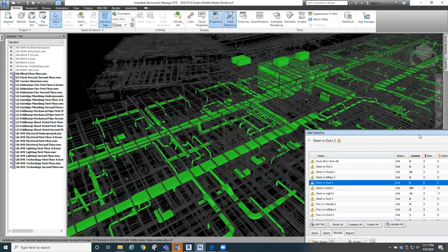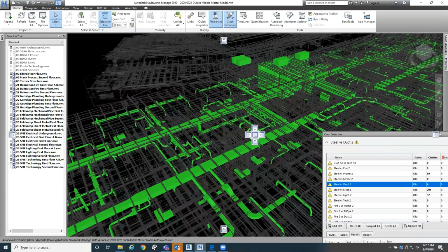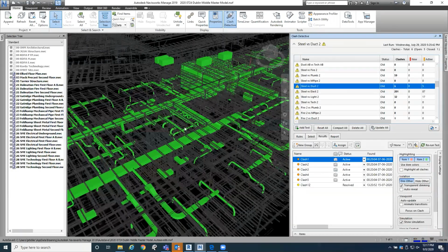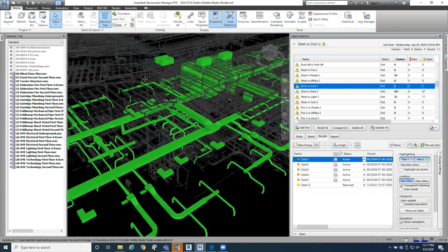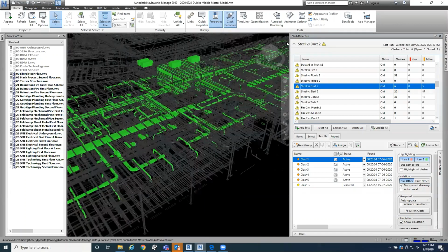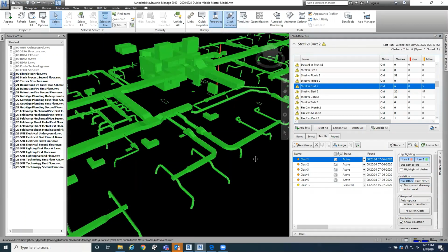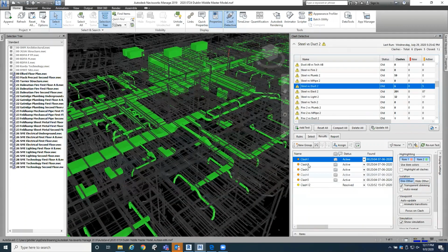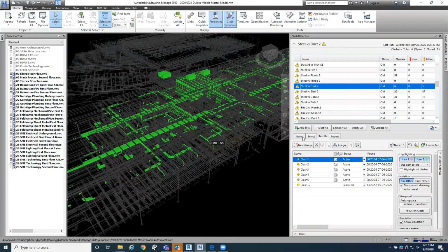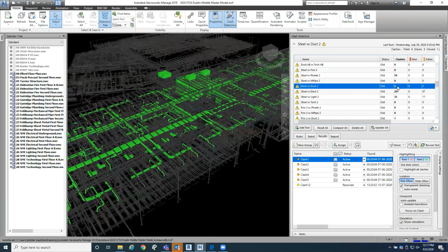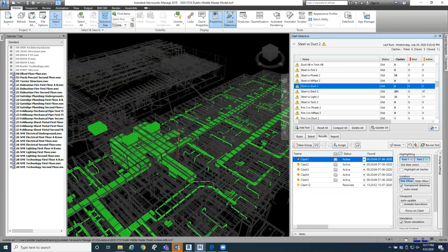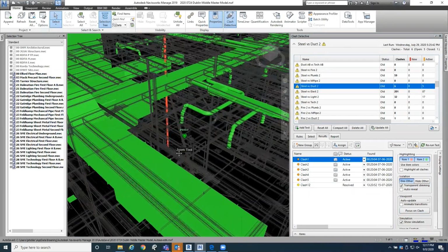That is one of the problems when I'm exporting these NWC files this way: sometimes the clash detection doesn't like to isolate a clash unto itself. So I'm highlighting everything here. I'll have to go find these 6 instances. It just gets me in the neighborhood.